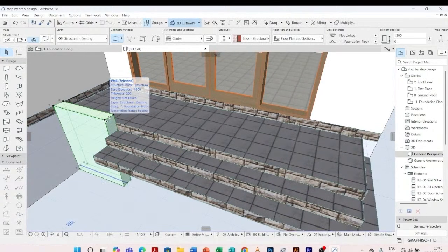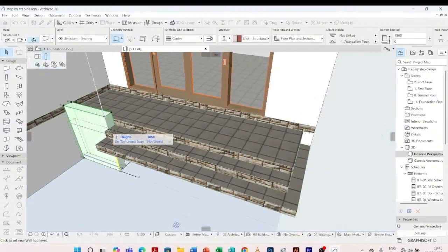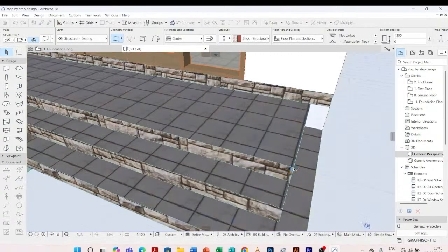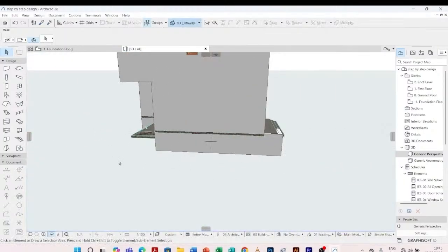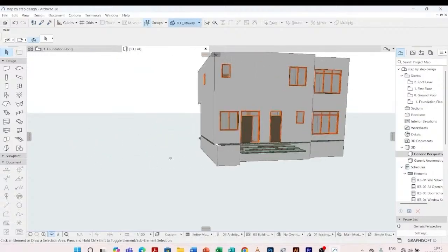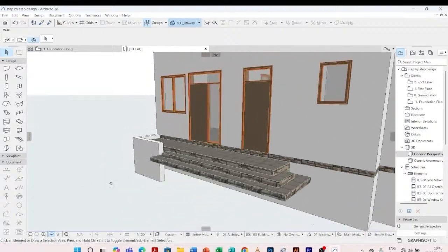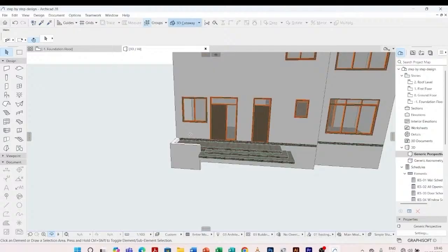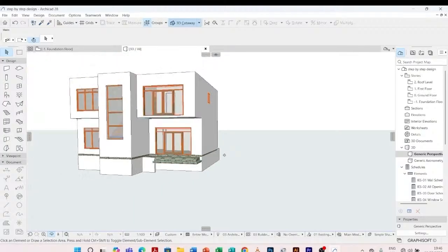I click on this black node. Then I come to this second option, which is called stretch height. So when I click on it, I can stretch the height of my wall. So I want it to end at this level. I'll do the same this side behind. But for behind I can leave it to overlap, because we are going to have some guardrails around there.